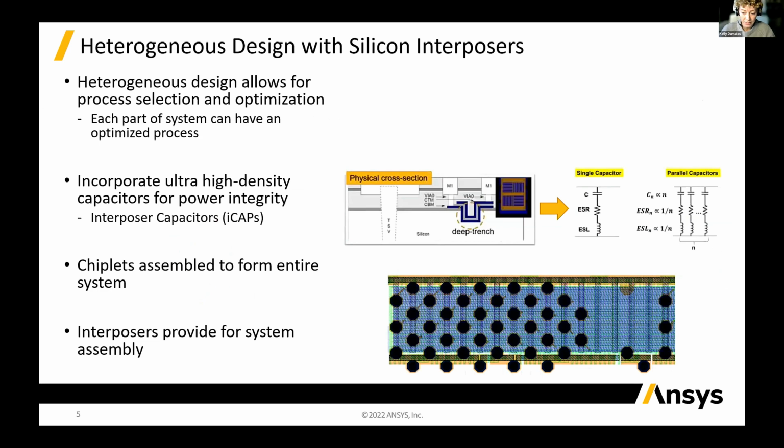Stacked 3D IC arrangements and side-by-side 2.5D arrangements help designers surpass the limitations of Moore's law by making it feasible to achieve performance gains at the individual chip, or practically chiplet, level. Significant performance and cost gains can be made with heterogeneous integration by using the most appropriate process technology for each chiplet in a 2.5D or 3D IC assembly.